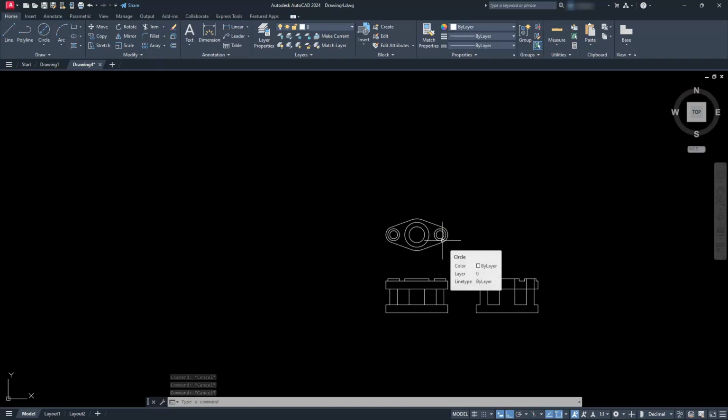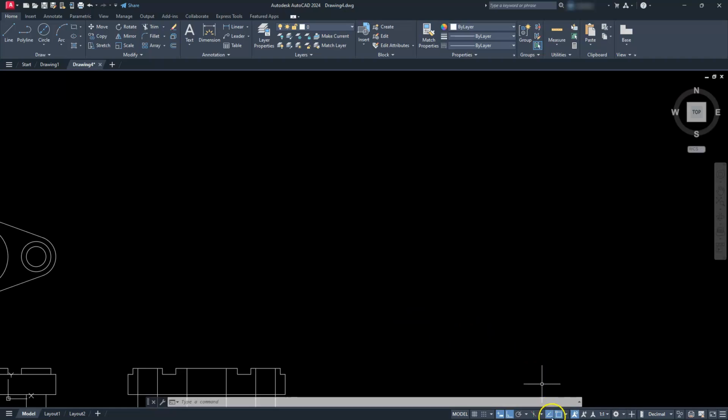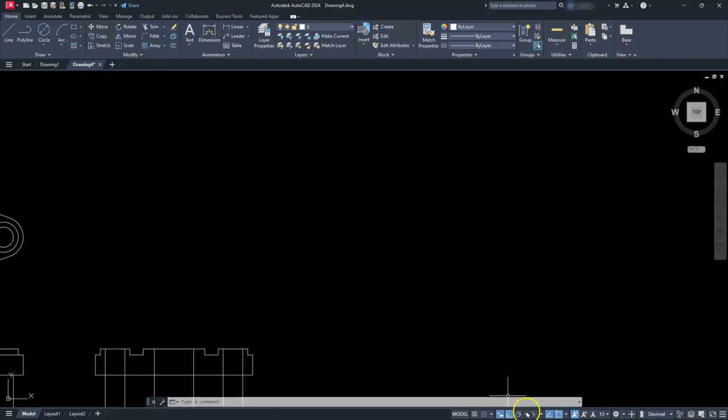Let's go ahead and start taking a look at drawing the isometric, right? So I'm still going to create the isometric, and it will still behave the same no matter if you're using ISO standards or the imperial standards, right? Or ANSI standards is another way of saying that. So let's start working on the isometric, right? So the first thing I'm going to do is switch AutoCAD over to isometric. The way we do that is we select this icon here, and then I'll go ahead and kind of flop between them. You can also use the function key F5, or you can select the flyout next to it, and I'm going to be on isometric top.